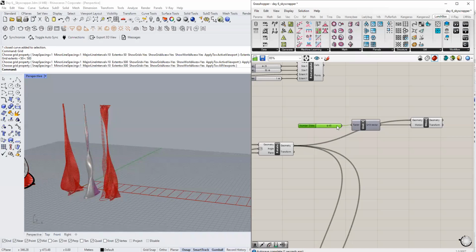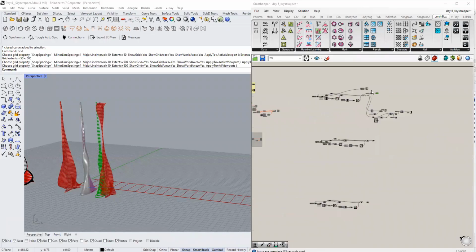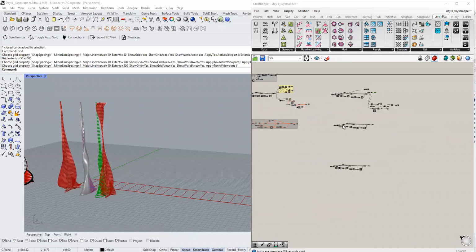It is going to move the entire tower as you're seeing in my Rhino screen. It does not move tower to the cell. It does not do that. When you give a vector like unit X, Y, Z, or even the normal vector, it's just going to move all the flow plates in a single direction. We do not want that. What we want is, let's just hide all unnecessary previews.